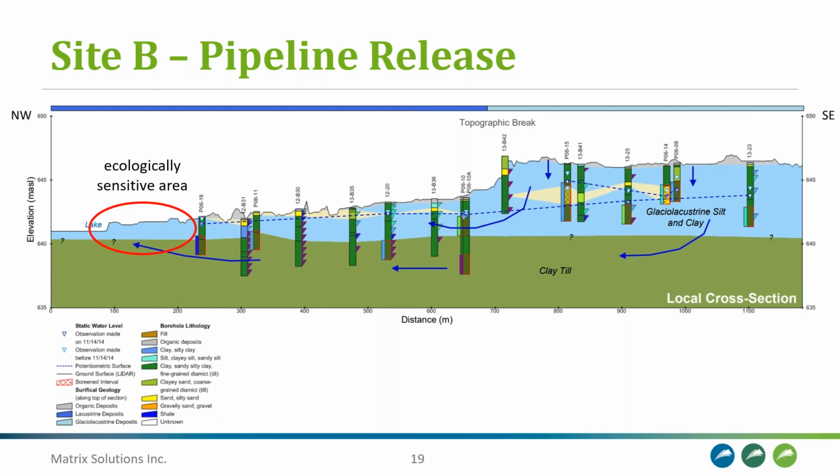So one thing to note is we couldn't install any monitoring wells or boreholes right near the lakeshore because this area was deemed to be ecologically sensitive, and this did somewhat limit our understanding of the downgradient impacts.